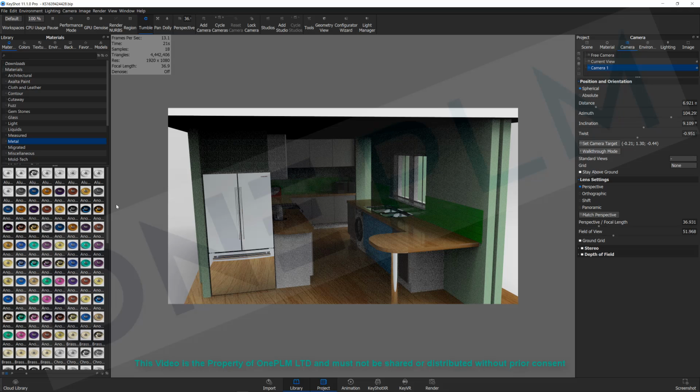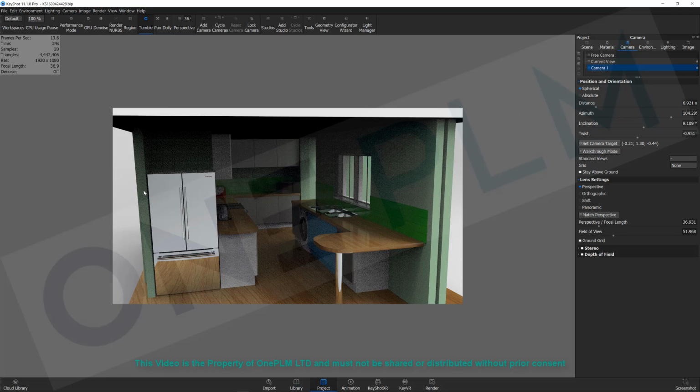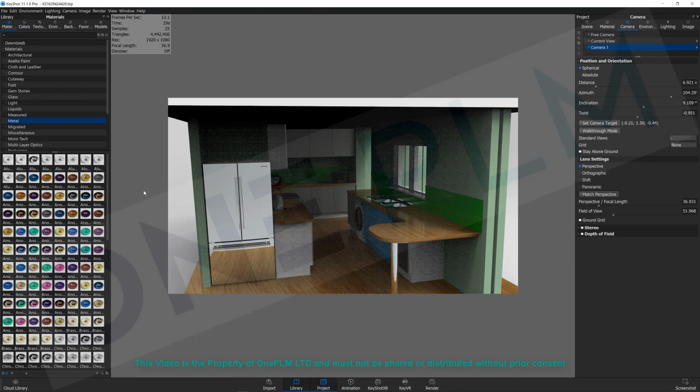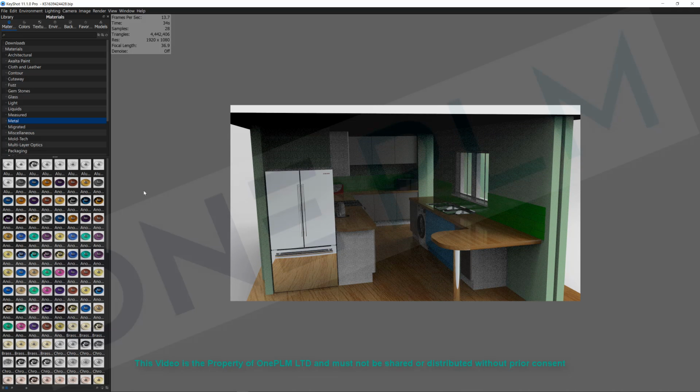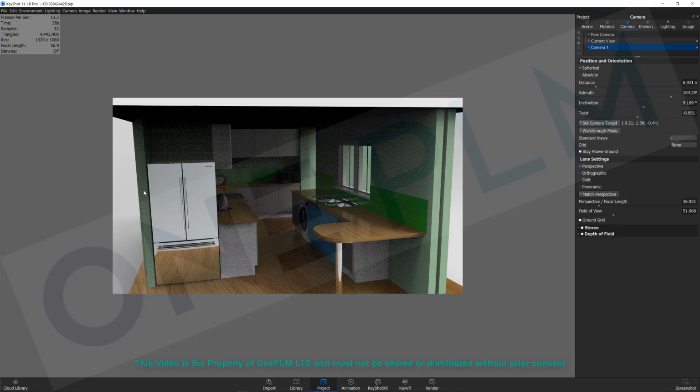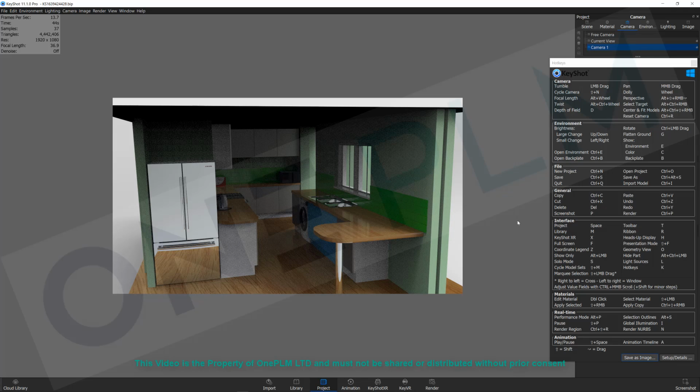One thing I always remember: M turns on the bar on the left. R turns the top bar on and off. Space bar removes the bar on the right, and T removes the little bar at the bottom. If you don't need one of those options, you can turn them off to give you more room. Also, if you press K on the keyboard, that will bring up the hotkeys.